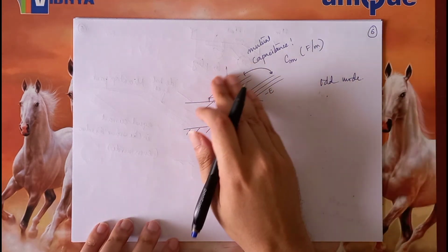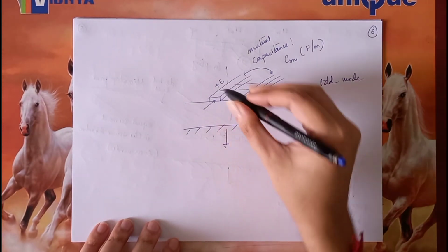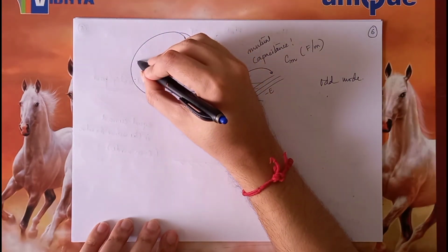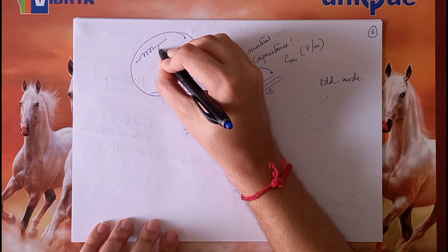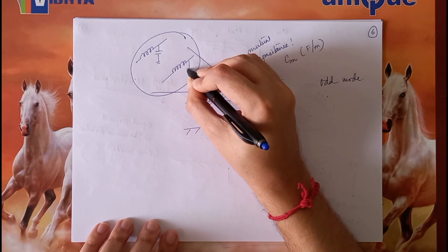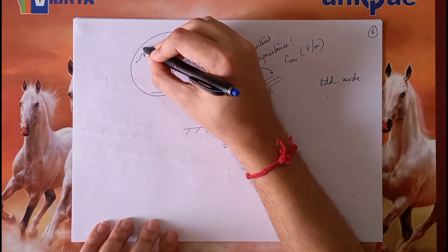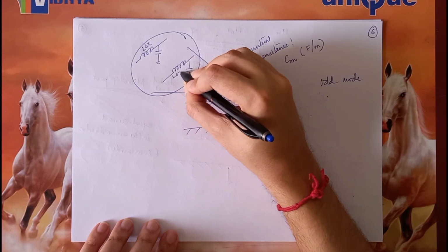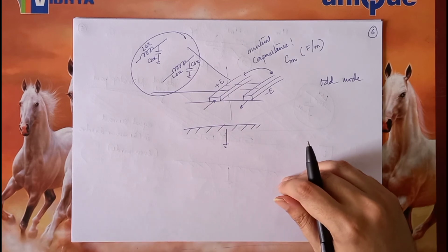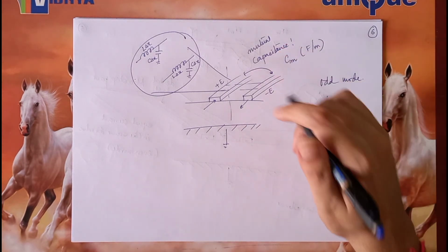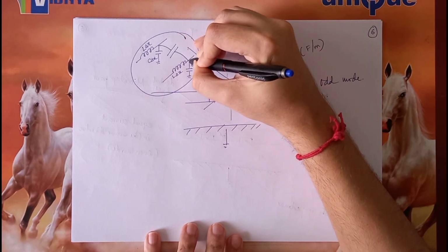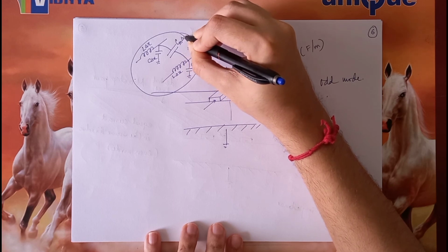So now if I look at these two lines with a magnifying glass, what I will see first are the two conductors which are first independent. This is L delta x, this is L delta x, C delta x, and C delta x. Now, the mutual capacitance here will be what? It will be like this, Cm times delta x.